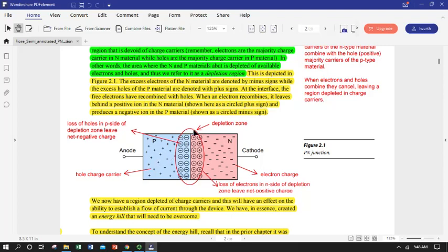So what do you think happens when all of those extra electrons and extra holes meet up at the interface? They recombine, and a hole and electron come together, and they annihilate one another. So the pluses and the minuses add together, and you get 0 effectively in terms of a charge carrier. That's called recombination, and it eliminates 2 charge carriers, just like promotion of an electron to the conduction band created 2 because it left a hole behind. Well, now we're going to get rid of 2 when they combine.